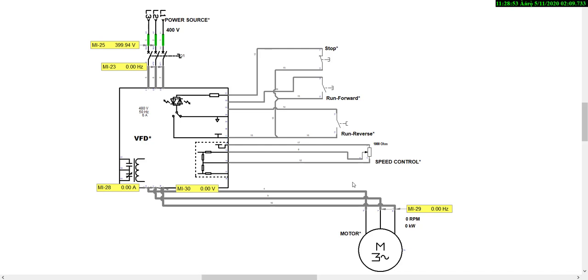So in order to be able to change the frequency of a signal, we have to select the best time to change this frequency, and the best time is during the process of inversion from DC to AC. So basically, a VFD takes in an AC signal or an already rectified DC signal and then converts it to AC, which technically is called inversion.